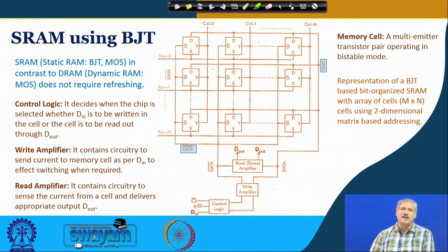In DRAM the number of parts required is less. Here the number of transistors and other circuit elements will be a little bit more. So in DRAM the packing density will be more, but SRAM will be faster, and refreshing is not required. So these advantages are there. More of DRAM we shall see later. Today we discuss this static RAM memory unit, and more specifically the memory cells.